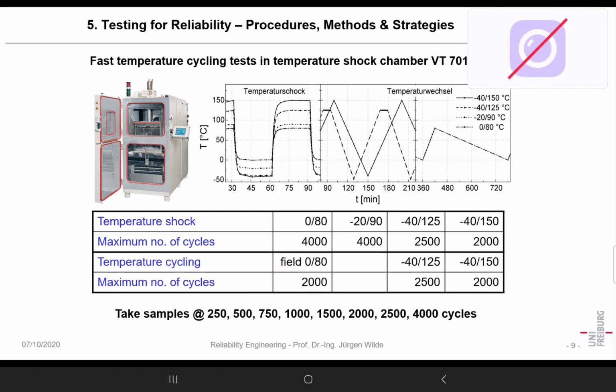Why is that so? Let's think about that part here. Now I do such a slow temperature cycling. When you look at the temperature distribution in that part, how is it when you cycle slowly? Yes, it's uniform, an even distribution of temperature in that part. Will that lead to stress in a uniform material?